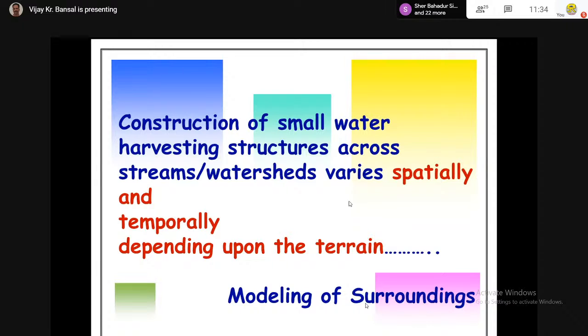Now, from there, it was converted into the shape file, 2D shape file. Now, these are the points which were taken with the help of total station on NIT Hamirpur surface. Now, after that, elevation Z value was assigned to all these points. Now, after this Z value, these are all those points which are now in space. Now they have X, Y, and Z coordinates. Another view of the same points in space.